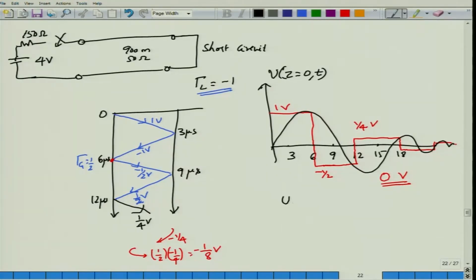Okay. So in order to obtain an underdamped situation, you need to have one of the gammas be negative. If both gammas are less than 0 or greater than 0, then you go to what is called the overdamped case, in which there would be a staircase kind of thing. So it would keep increasing and eventually reach the steady state value.